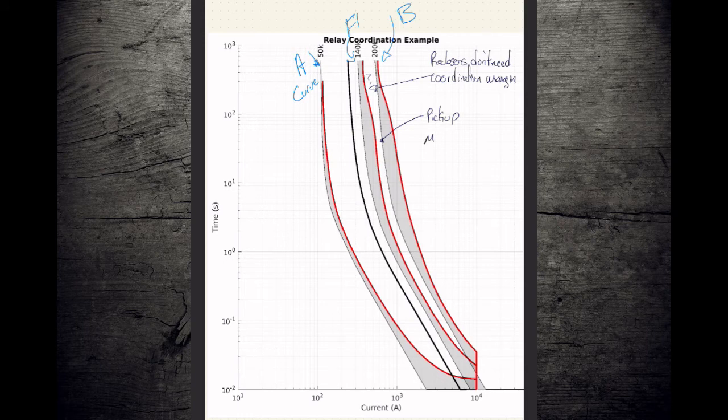We still have a clear or a max clear. And this is the time by which you're guaranteed that the breaker or switch has opened and snuffed the arc, breaking the conduction. There's no more electricity flowing. Circuit is open.